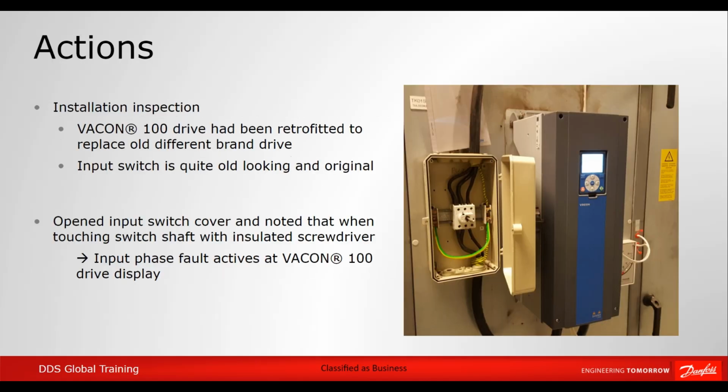Based on customer information, the VACON 100 drive had been retrofitted to replace an old drive of a different brand. Installation inspection shows that the input switch looks quite old, and according to the customer, the input switch was not replaced during the retrofitting of the drive. Therefore, the input switch cover was opened and it was noted that when touching the input switch shaft with an insulated screwdriver, input phase fault, fault code 10, activates at the VACON 100 drive display.